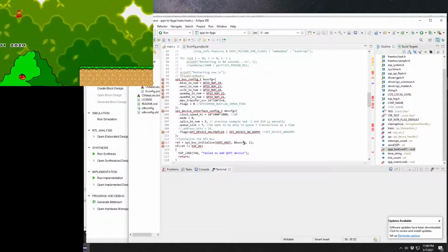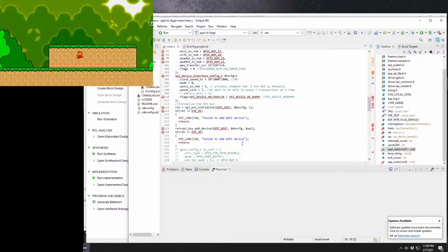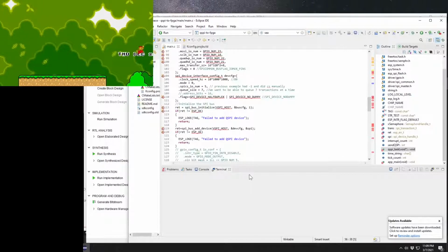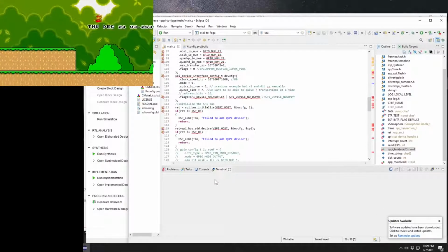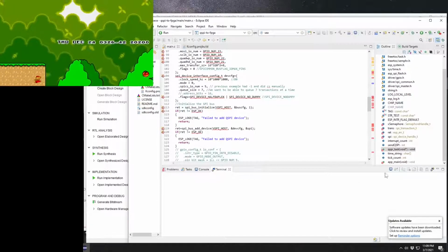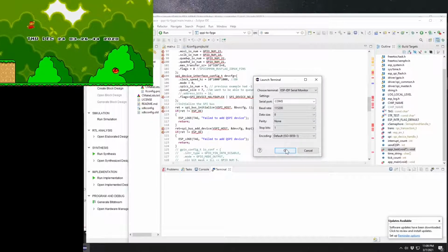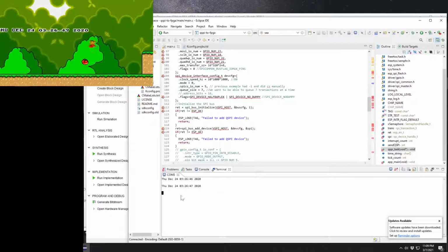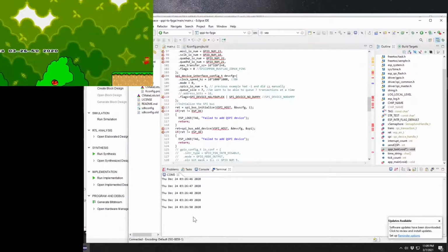Like I said, I really would like to get this brought into Arduino. I think it's a lot more approachable. You can also run the ESP IDF through the command line, but at least I found on Windows the experience in Eclipse is a lot better. One big reason for that is, you see here I have a terminal. Within my terminal I can actually connect to the ESP32 that's on the chip, and I can continue to receive regular updates from it on serial.